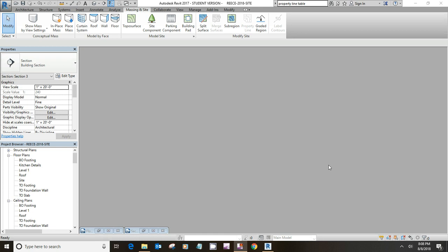If you're working for a residential builder, you'll probably get a paper site plan or a PDF file, and it'll be a pretty simple site plan, and you could actually draw it in place in Revit like we're going to do here. If you're working for a commercial design firm, then you're going to get a 3D CAD file or survey point data from a civil engineering firm. The best way to deal with those is to link them to your Revit file instead of drawing it or inserting it into your file. But we're going to actually draw it.